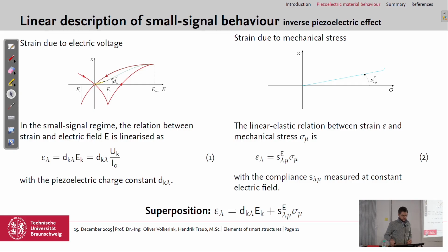If we look at the strain, we have two effects which contribute to the strain. On the one hand, we have the relation between strain and electric field, E. So we have the strain in the direction lambda, which is equal to d, the piezoelectric charge constant, times the electric field.